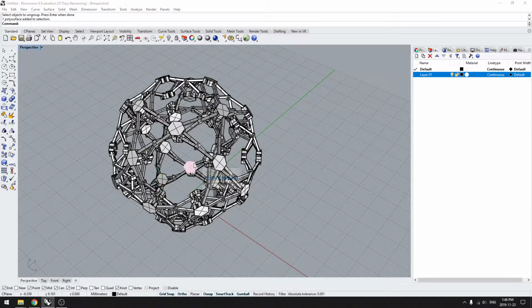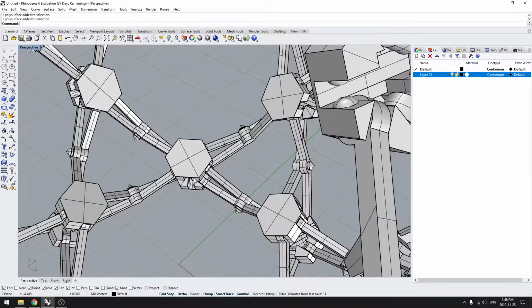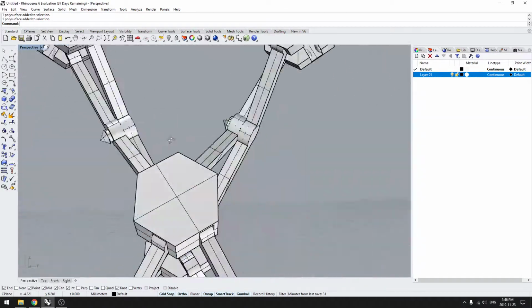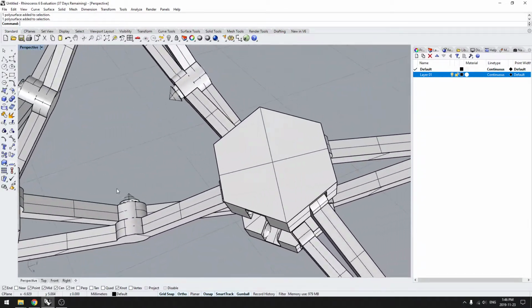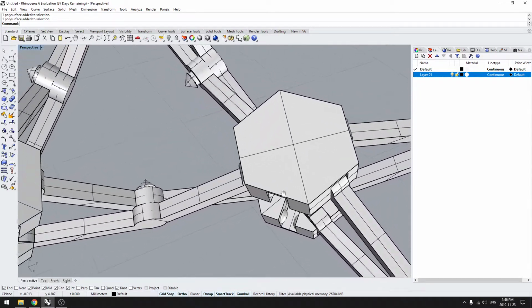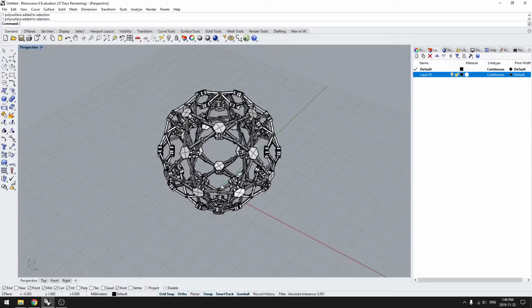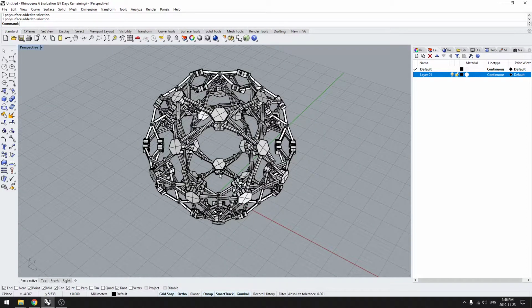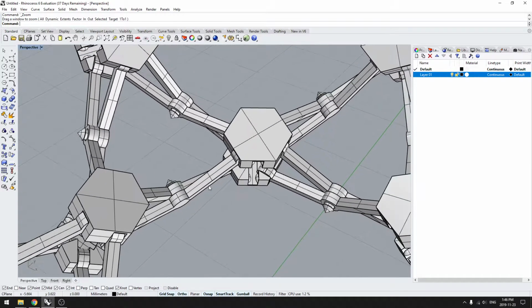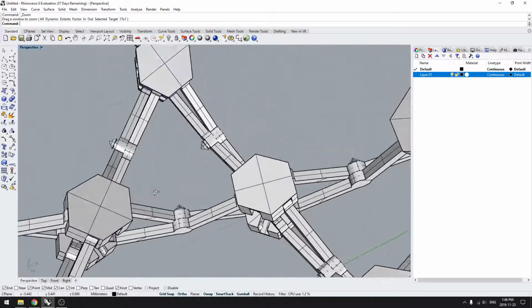And so what if I want to get in here and take a look at this piece in particular, right? Usually you'd be like, oh my god, I'm zooming, but you zoom and then it's kind of hard to move the camera now. The camera only moves so little because you're super zoomed in, right? So what you can do in this case is use the zoom command. You can just type Z and drag a window to be your new camera space, basically your new viewport, and it'll move you to that location and you get zoomed in.